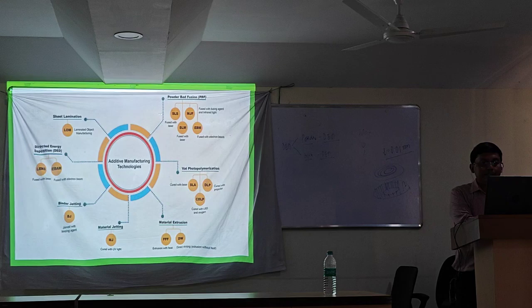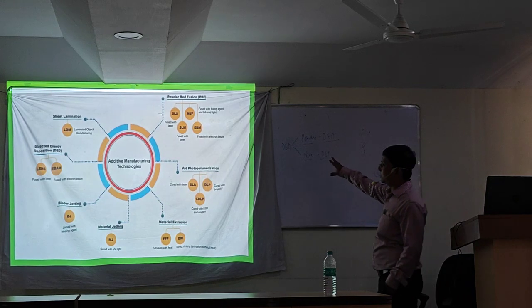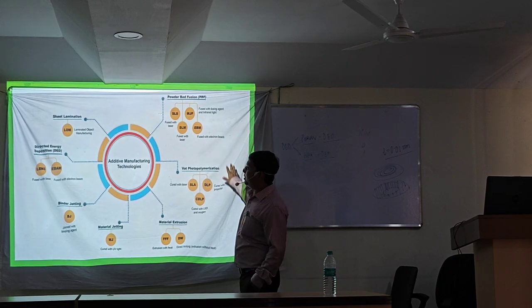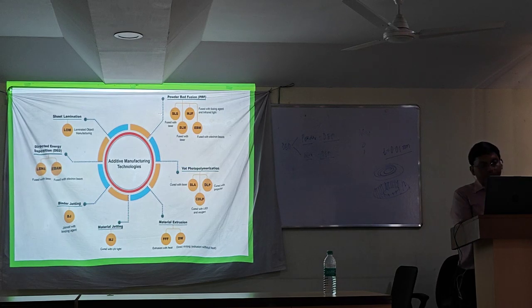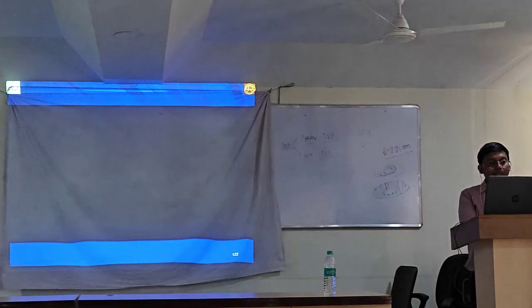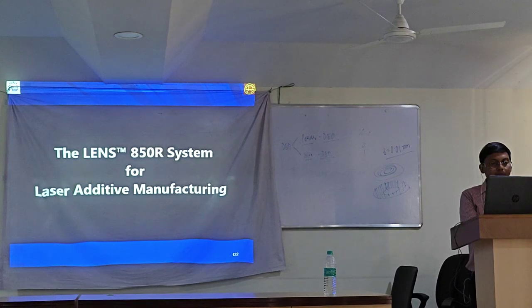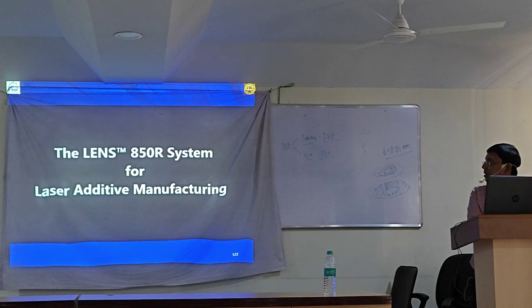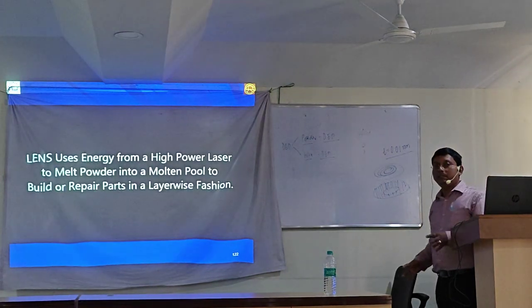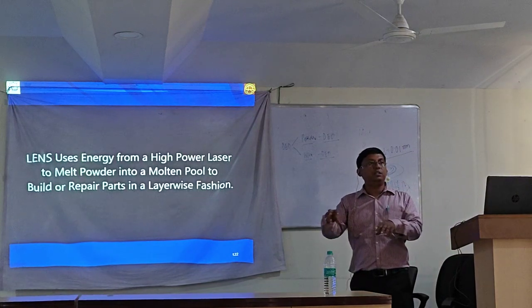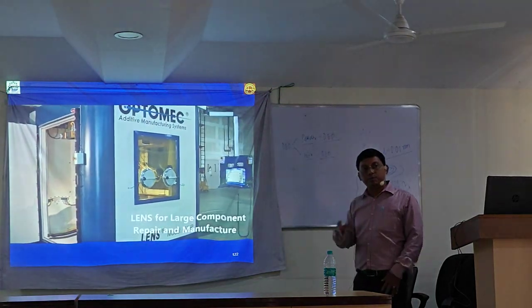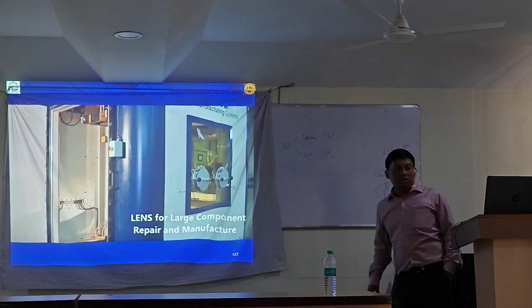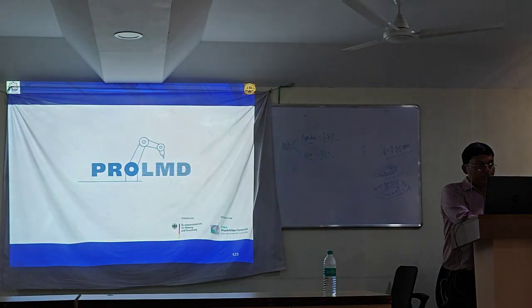So we have discussed the different additive manufacturing processes here. So I think we covered all 7 additive manufacturing processes. Now we would like to end up with a few more. One is some kind of hybrid additive manufacturing. Hybrid additive manufacturing means additive manufacturing along with traditional metal cutting or laser-based processing, so that post-processing is also done simultaneously. So I would like to skip this video.